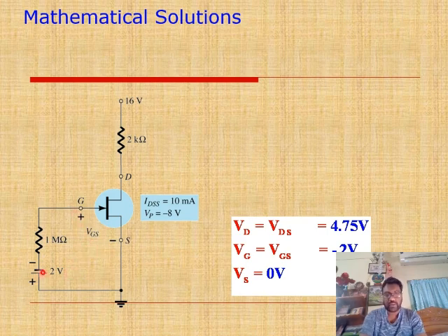So respective to that, we will get exactly minus 2 volt across this gate and source terminal. Though in practical cases, some of the voltage will be lost in the material as heat, but as we are using a very high resistance, that will be very minimal, so we can neglect those losses. So exactly the voltage we provide in VGG will be reflected across VGS.